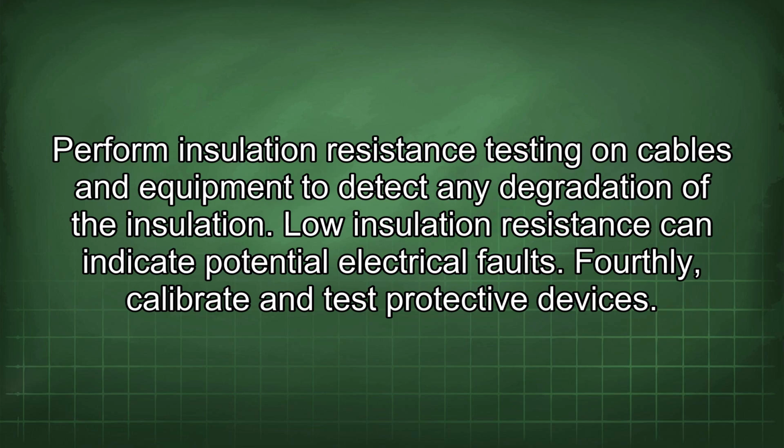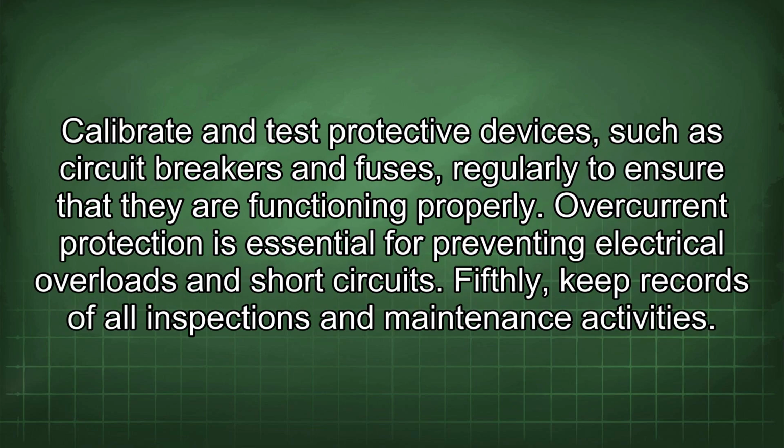Fourthly, calibrate and test protective devices. Calibrate and test protective devices such as circuit breakers and fuses regularly to ensure that they are functioning properly. Overcurrent protection is essential for preventing electrical overloads and short circuits.